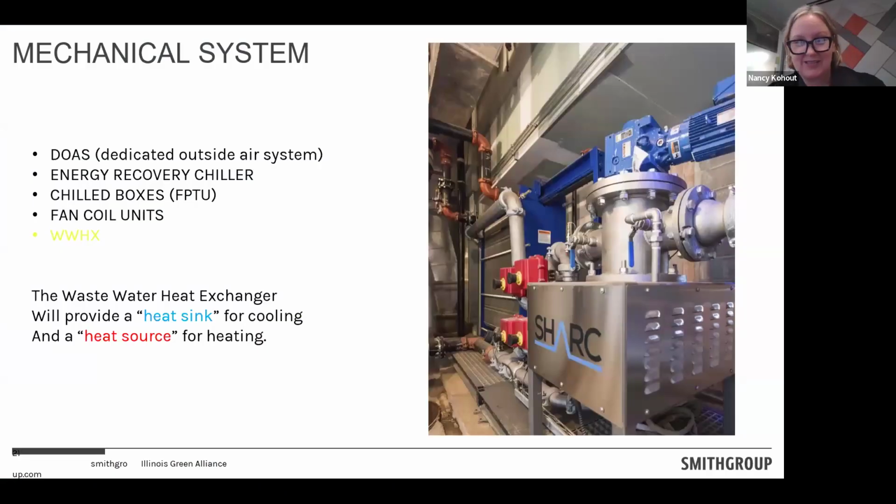And then, of course, as a mechanical engineer, this is the stuff that I think is really interesting to look at. So this is, we utilize the Shark system. So this is the system that actually we utilize to take the wastewater and run it through a heat exchanger to provide condenser water, which is like utilizing a fluid. Just like you do in a regular building with a chiller, you'd run that through a cooling tower, but we run it through in this building a heat exchanger to kind of exchange heat with the wastewater.